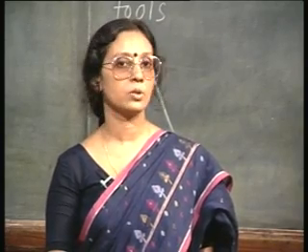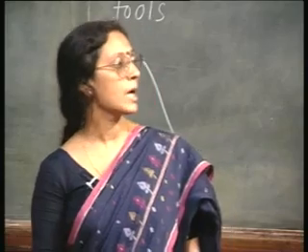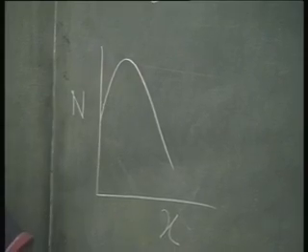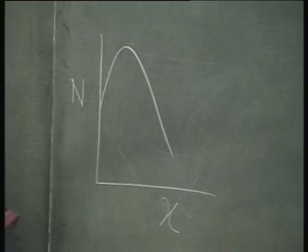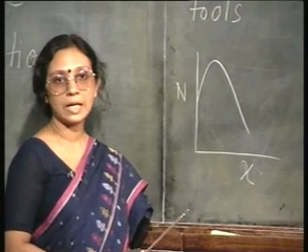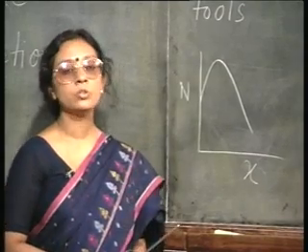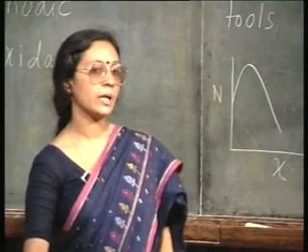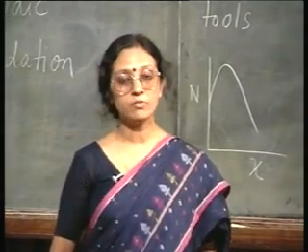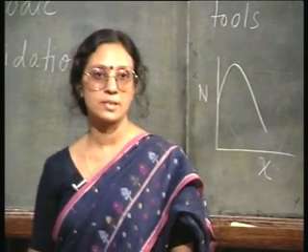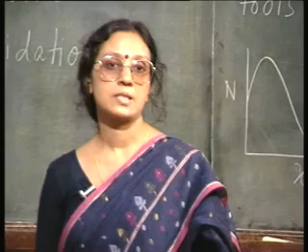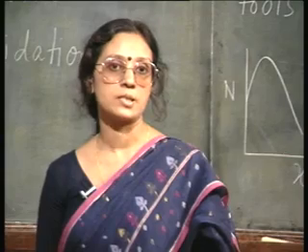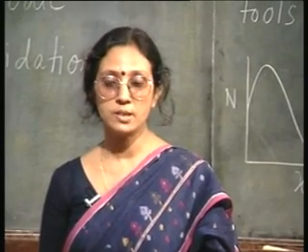So, that can be very accurately determined, the thickness of the oxide, and you can etch that oxide and measure the surface properties of the fresh surface thus exposed, and keep on continuing doing that in order to obtain the full doping profile. So, even though anodic oxidation is not really compatible with VLSI technology, it is not a standard processing step, thermal oxidation is the standard processing step, not the anodic oxidation. So, even though it is not a standard processing step, it still has its usefulness, it can be used as a diagnostic tool.